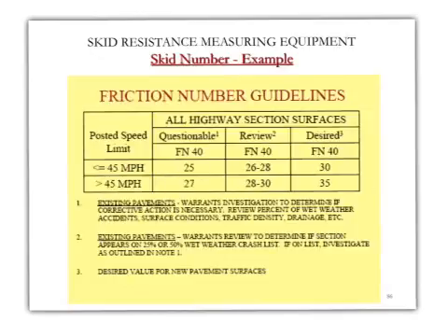We need the road to give us a good amount of skid resistance, because at higher speed we know that we need more skid resistance to keep the contact between the tires and the surface. If the speed is less than 45 miles per hour, those are the recommended values for the skid resistance. What is FM40? By the way, FM40 is the skid resistance measured at a speed of 40 miles per hour. This is the friction number, or the skid resistance number, at 40 miles per hour.